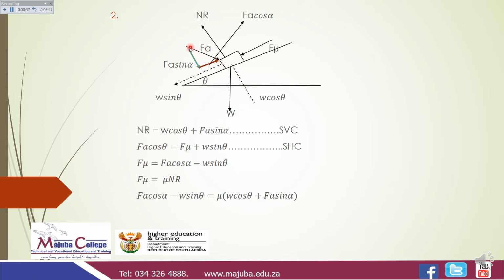So you will have the vertical component, which will be your perpendicular force, and the horizontal component, which will be your parallel force. How do we get their magnitudes again? For this vertical component, it will be opposite to your angle. So the trig ratio that uses opposite and the hypotenuse will be sine alpha. So the magnitude of this vertical component will be FA, the sine of alpha.